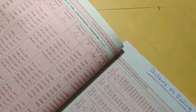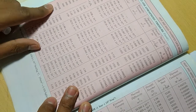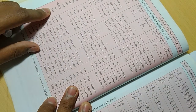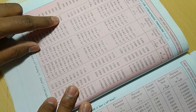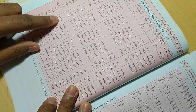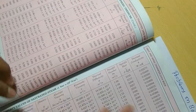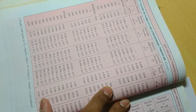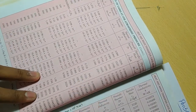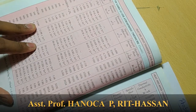In page number 33, air is there, but what we require is the steam. Here 100 and 120 are there. For 100 degrees, the density of the vapor is 0.598. For 120, I have taken 0.590. I will take 0.590. You just have to do some manipulation to get 120 degrees centigrade. You take a value less than this, or you can take 0.58 also. That is not a problem, because it's a very small difference.